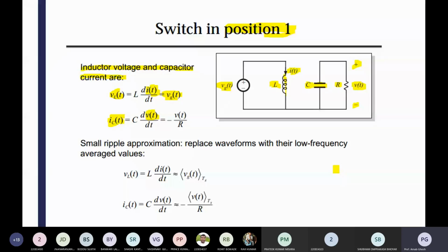We also design some nonlinear controllers, like the geometrical attractor based, trajectory based controller. You know that some terms are very popular right now: sliding mode controller, predictive controller, Kalman filter based controller. A lot of controllers are there, but which one is perfect, which one is suitable for our specific converter, that is most important. So how do we get that? That is the modeling, where we get the expressions of the state variables.